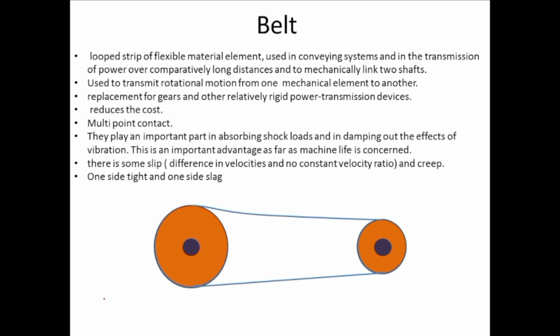Another important thing is that for the transfer of motion or power, the friction is important, and friction can be increased by increasing the frictional area. In case of no sag, the belt will be straight. So let's say at this point the contact between the belt and the pulley ends. But if there is a slack, it will be like this, so the contact will end at this position. So due to the slack, there will be an increase in the frictional area, and because of that the motion or the power will be transferred very easily. So these are the two importances of the slack.